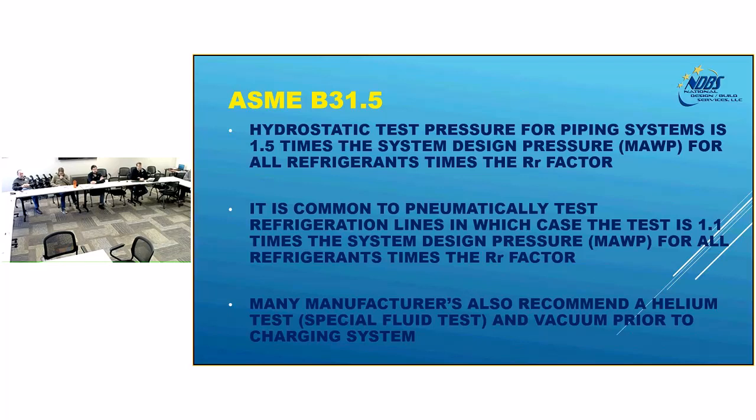So kind of the same story as B31.3 for the hydrostatic test. Now with refrigeration systems, because they're much smaller, it is commonplace to pneumatically test them if it's a small system. And a lot of manufacturers also require a vacuum test prior to startup.